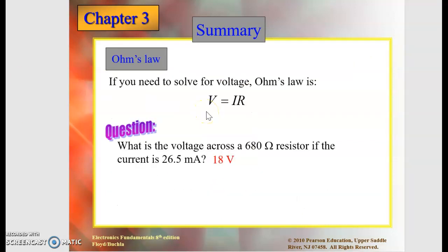Here they solve for voltage, and they are saying use Ohm's law to solve for voltage, given that you have the current and you have the resistance. Be very mindful and careful with the milliamps. That means 26.5 times 10 to the negative 3 amperes. You plug in here and then you should get 18 volts.